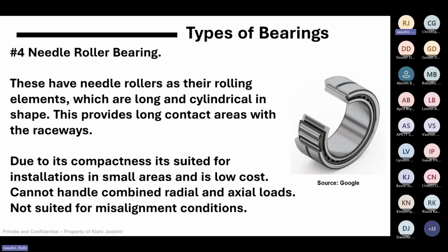There's also a smaller type of bearing known as a needle bearing, which is a variant of the cylindrical bearing, but has smaller or narrower cylindrical elements. More used where we have limited space available and also limited in its load carrying capacity. And they have many variations of these other types. They are tapered roller, tapered needle, and it's just a combination in terms of your application.